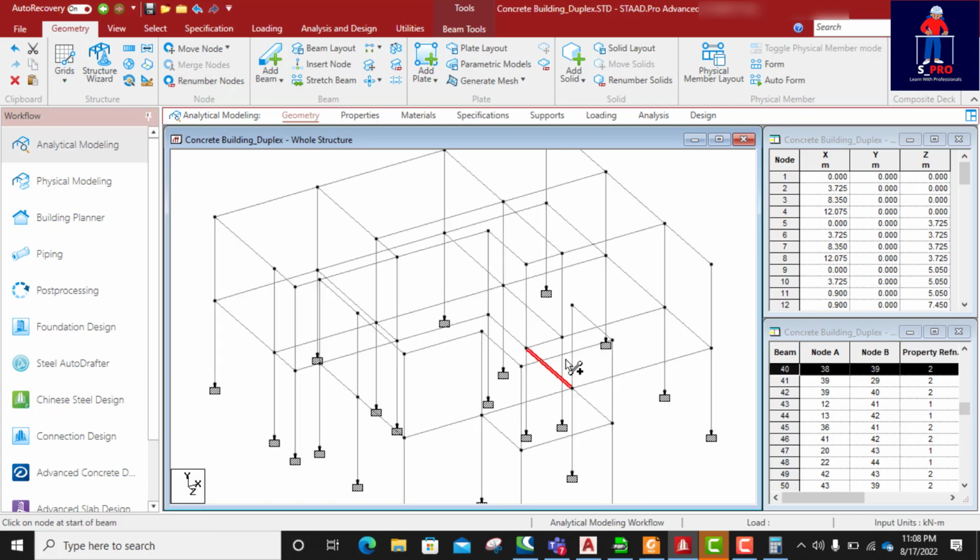Okay, click on my beam, connect this to this. That's good. Then this one is connected to this member, so that my long beam, yes, supposed to connect here. So that's the issue. That's why you should always cross check the members you have selected.